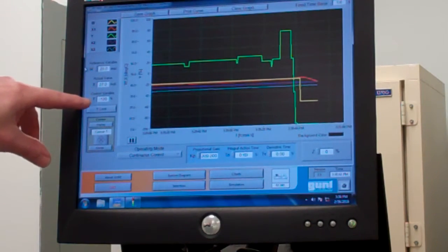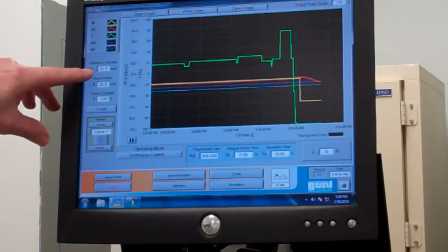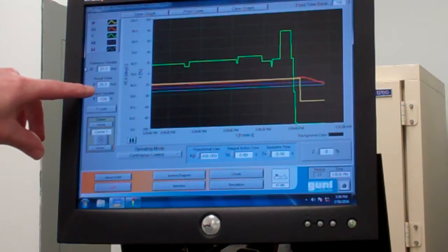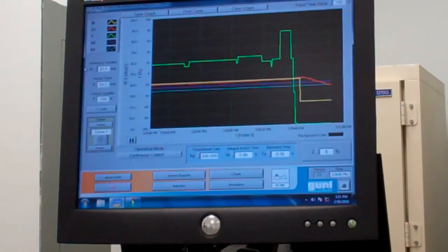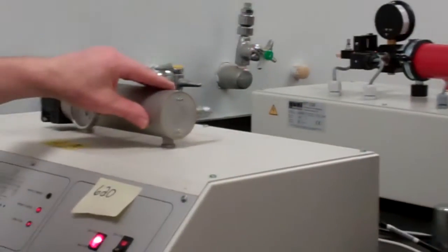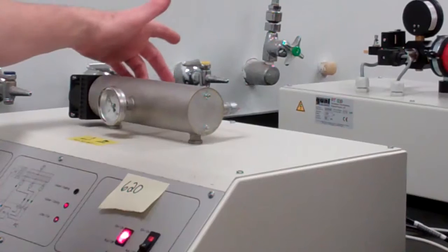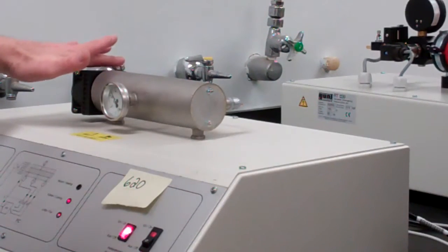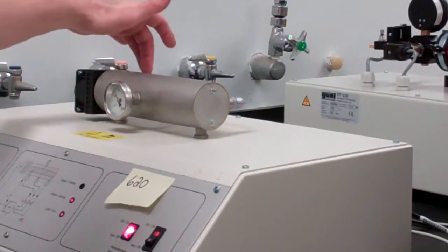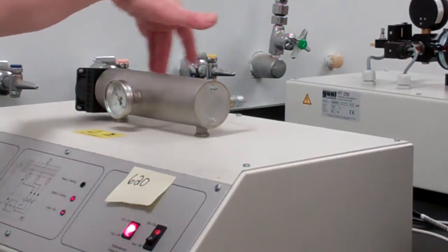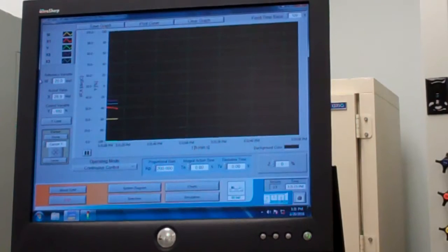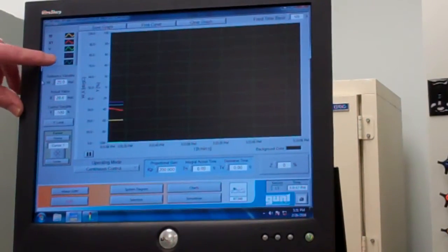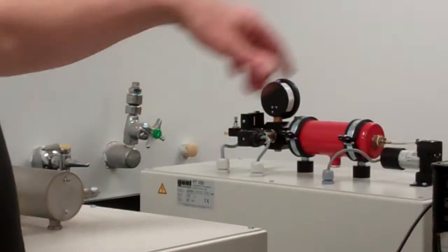what these W, X, and Y mean, but basically this is your set point here. This is the actual value here, and there's actually 3 X's because there's a metal bar in the middle of this insulation, an aluminum bar, and there's 3 temperature sensors, and the heater is actually down here on this end. So this is the first temperature, X1, that's represented here. Second one here is X2, which is this one in purple, and the third one is X3.